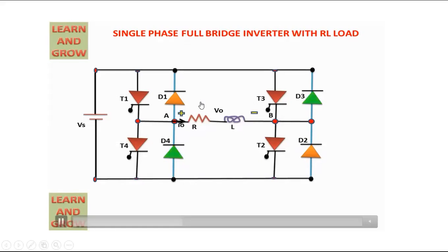Okay, right. So what is case 3? Anyone tell me? Now current is flowing through the load in one direction. Now you can see, now I am passing the current in opposite direction. So case 3 is T1 and T2 are turned off and T3 and T4 are turned on with the help of UJT firing pulse. That means case 3 says that with the help of forced commutation circuit, we turn off T1 and T2.